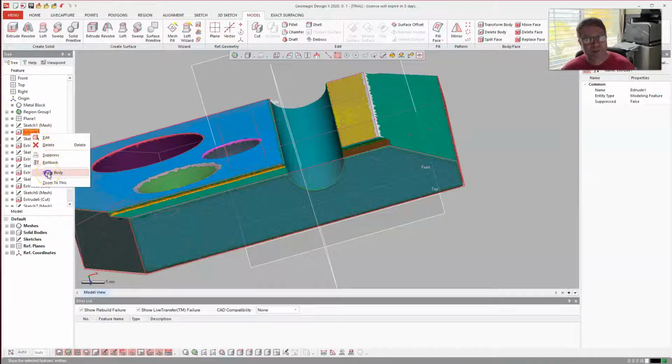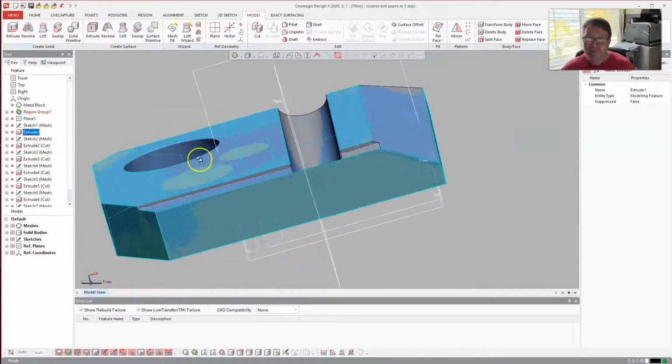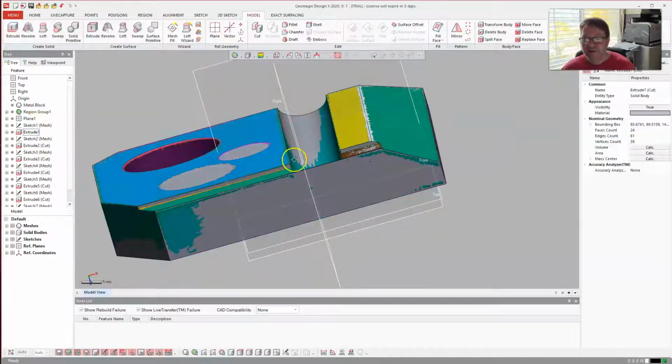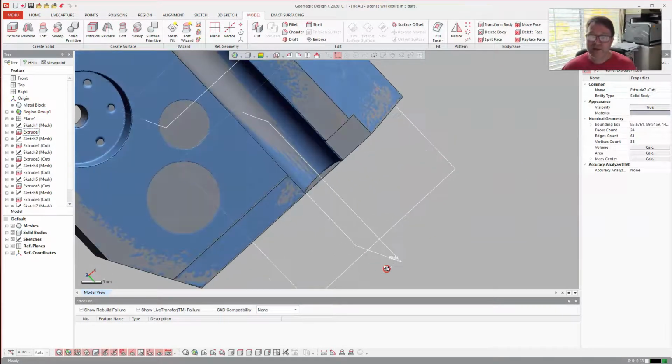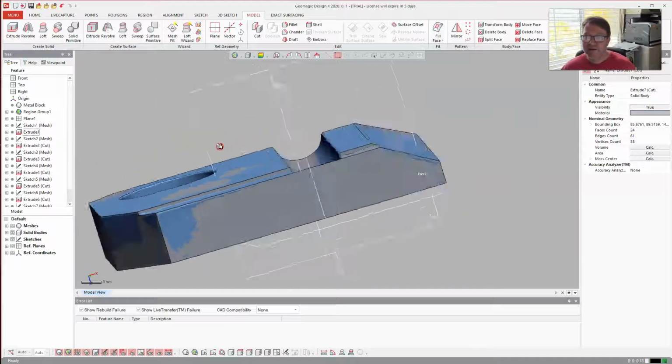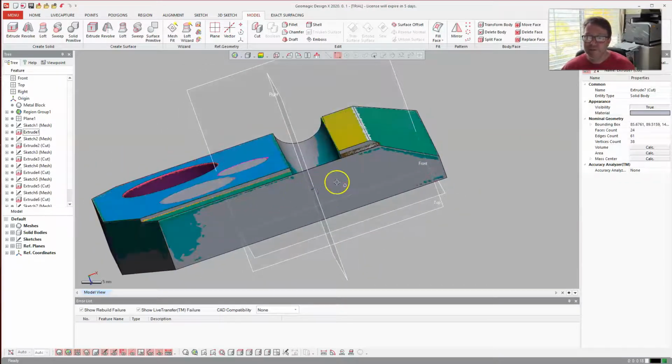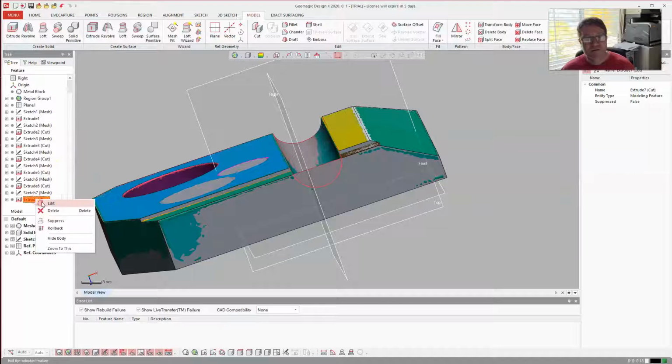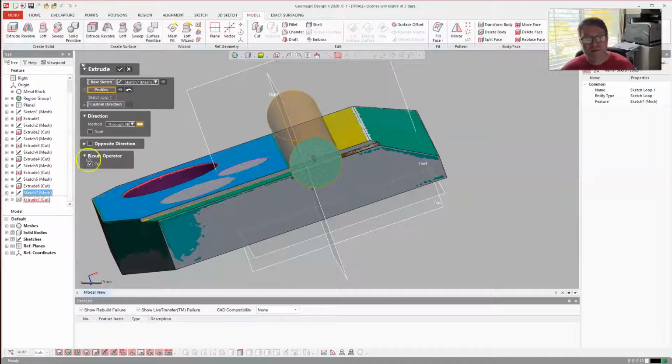Extrude 1. Once again, notice how there's actually a very thin plane because it's not perfect. So there's a very thin plane right there. So if I go back to that extrude, make sure you do both directions. Only have to do that much in the other direction. Control 1. Now I've got that shape.